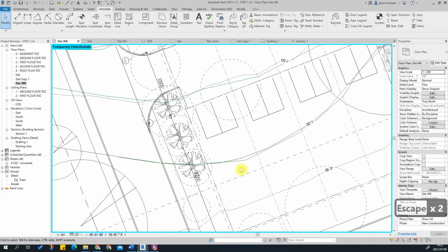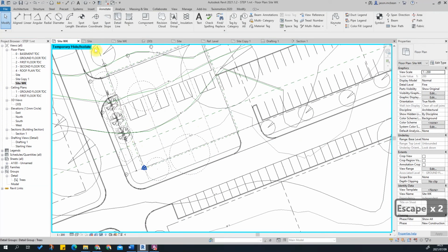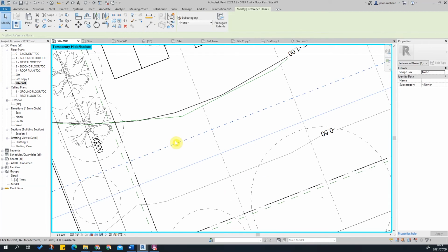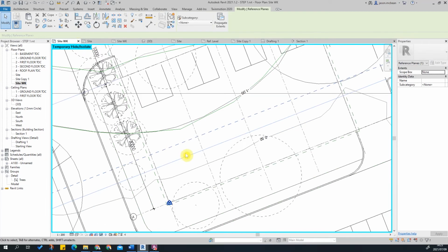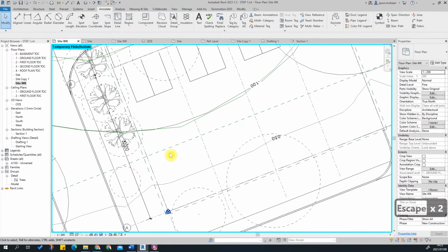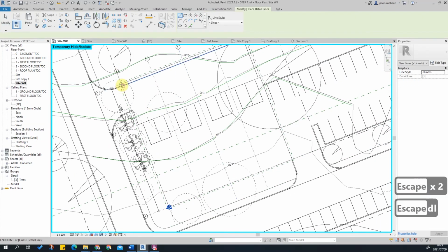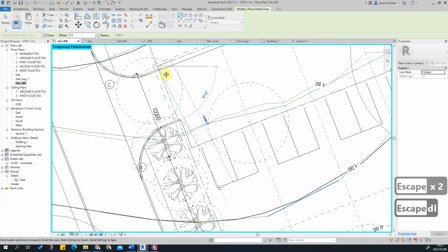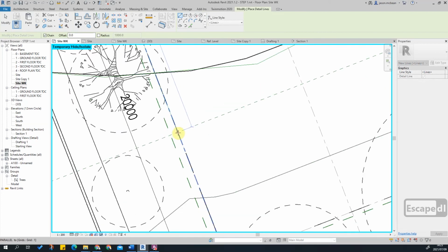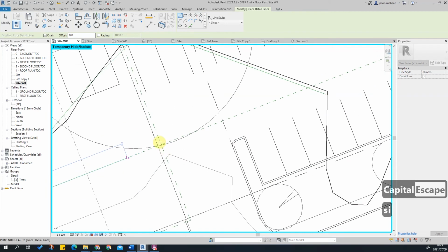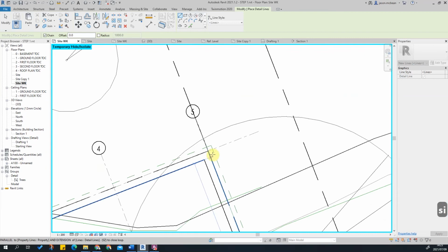So here, from this line, I've got a basement. So from there onwards, it's minus 2. Now that's the first line. I usually offset this by a certain amount. I'm going to use a detail line again. So this time I'm going to use a closed set of detail lines, explaining why I'm doing this. So snap intersection, SI, snap intersection, boom, follow this line. There we go. I'm going to close this line work to there.